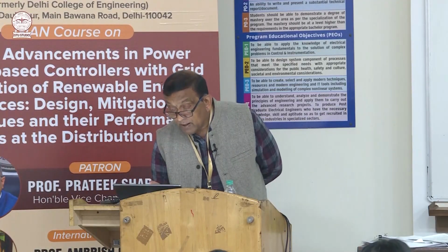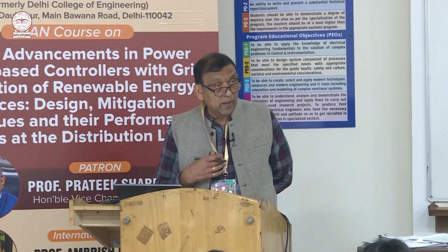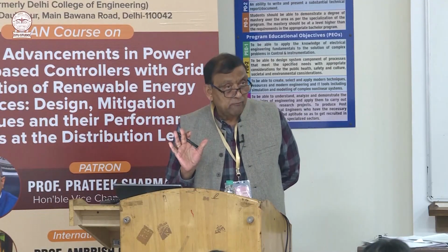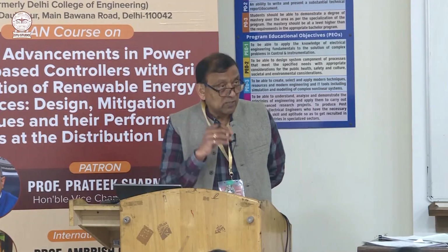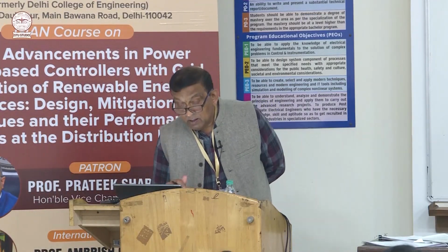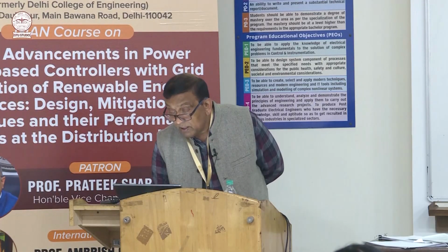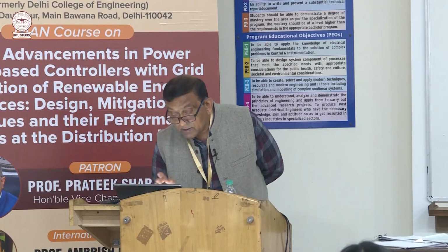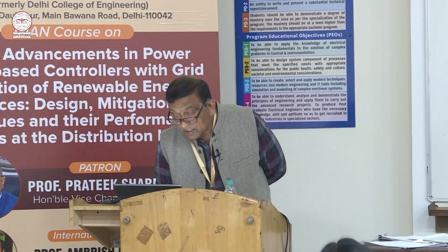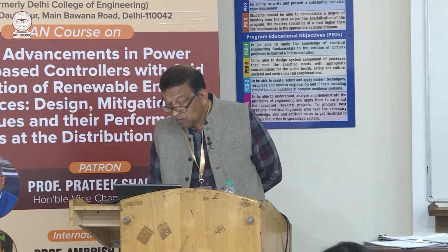There's a lot of development going on in this area. Recently, many articles, even few years back, we wrote a very big review paper on multipulse technique with Professor Bhim Singh, and you will find so many articles and so many multipulse techniques. Two major advantages of multipulse system: decrease in current harmonics on AC side, decrease in voltage ripples on DC side.